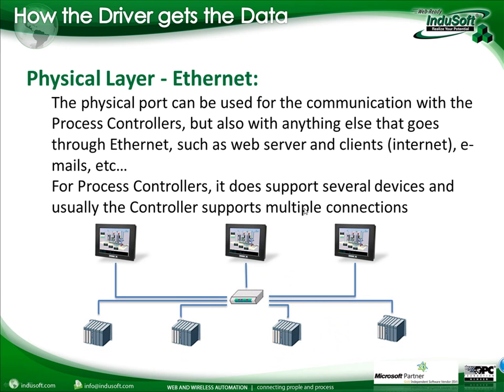And then nowadays you have lots of controllers with Ethernet capabilities. As I said, if you compare the baud rate of an Ethernet connection with that of a serial connection, the lowest Ethernet speed is 10 megabits per second, while the fastest you're going to have on serial is around 115 kilobits per second, so it's already much faster. But most Ethernet nowadays is 100 megabits per second, and even 1 gigabit per second. So that already gives you an idea of how much more data you can exchange through an Ethernet channel.